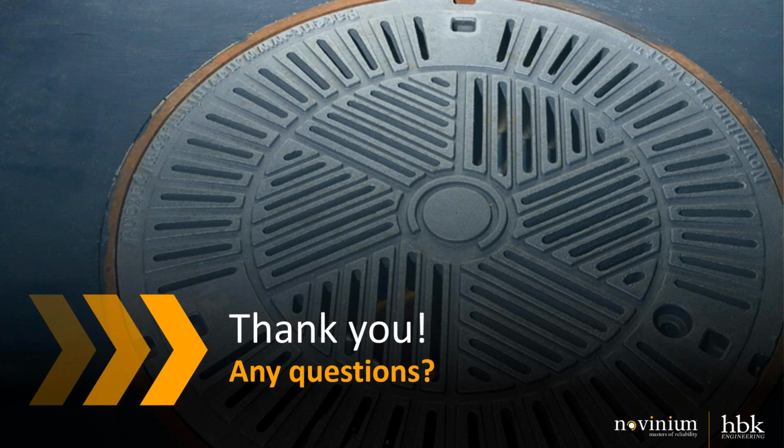Yeah, so it depends on which part of the country we're in, but typically we measure the gases that cause issues like the fire, smoking, and basically the explosive events. Carbon monoxide was one of the main culprits that we watch. The other one would be methane, or CH4. And in a lot of cases, where maybe we have organics that fall into a manhole, we might be watching for H2S. And then also, are there any flammables that might occur inside a manhole.